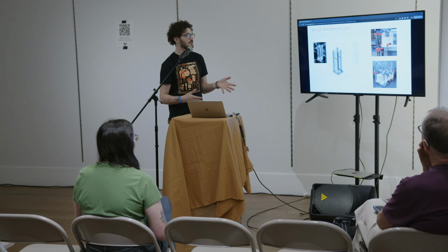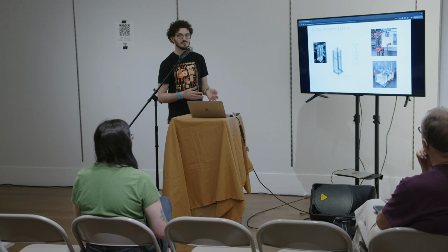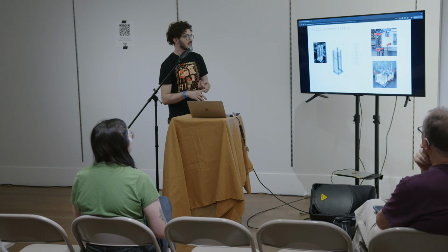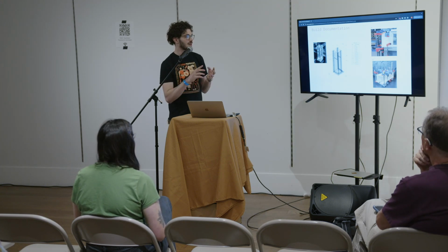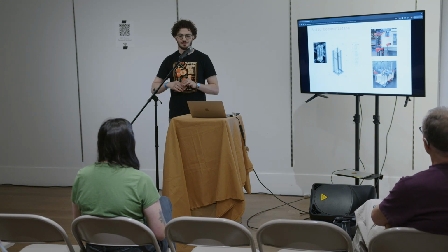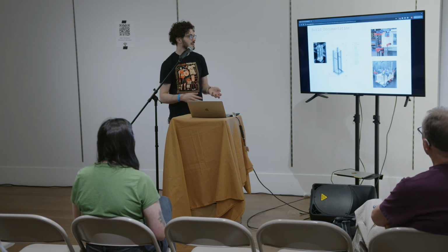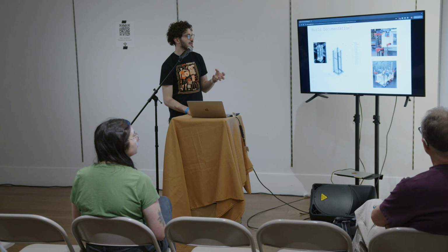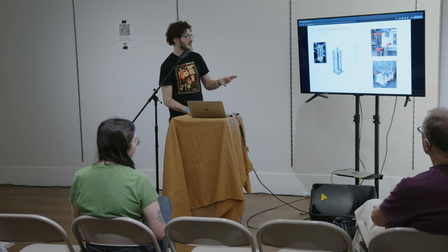But one of the best tools for producing these build guides and build docs was the CAD files themselves. So things like programmatically naming the parts that go into the assemblies and then carrying those names through the documentation, the CAD, and the cut sheets makes it a bit more legible. And I think it's also useful to have photos of the real things so that you can connect the CAD to reality.